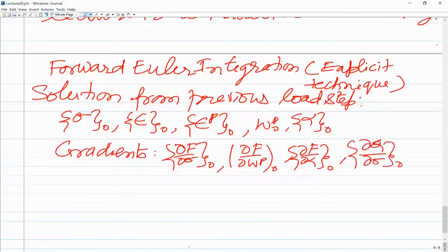So all these are calculated from the previous step, and we have some strain increment from Kt delta D equal to F. We would have calculated delta D, then extracted for a particular element delta DE, and from that we would calculate delta epsilon at a particular Gauss point. This has to be done again at every Gauss point. So from this we know the strain increment.